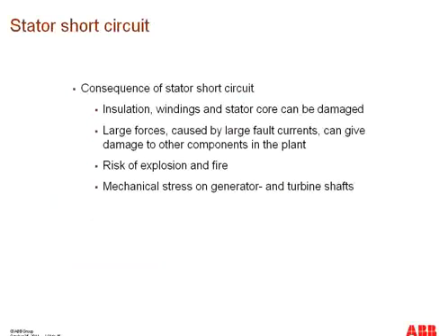Let's see the stator short circuits now. Phase-to-phase short circuits in a generator are relatively rare, but whenever these kinds of faults occur, the consequences are quite serious. When the short circuit occurs, the insulation is damaged, and due to the insulation damage, there are dangers of damaging the winding as well as the stator core.